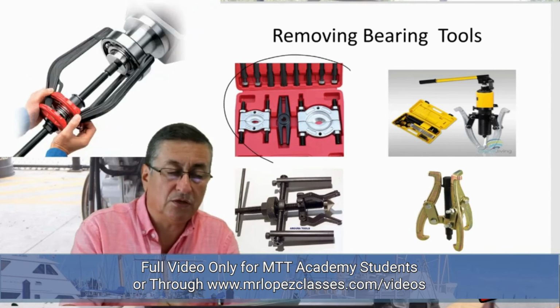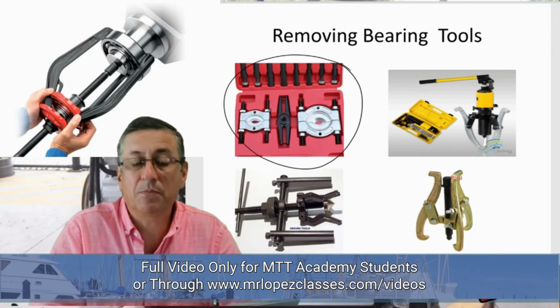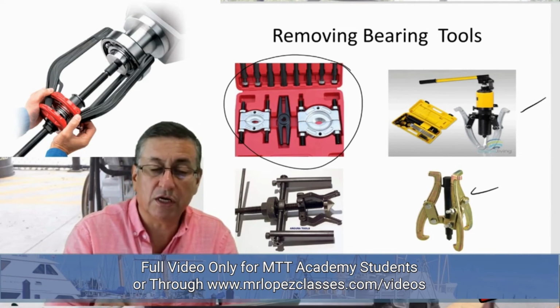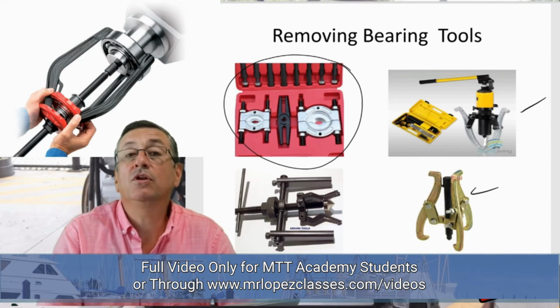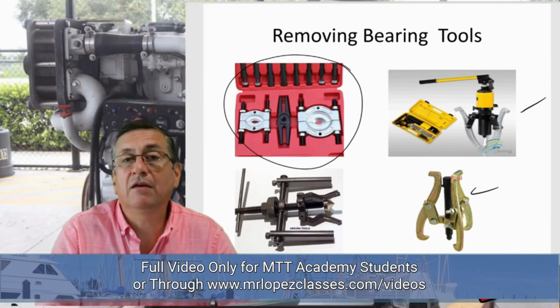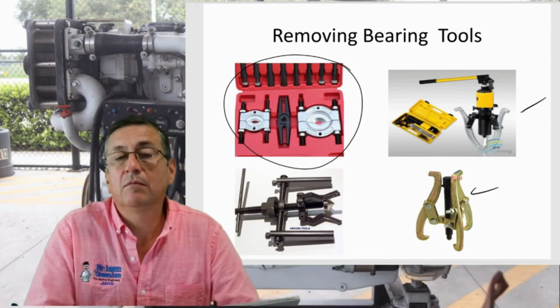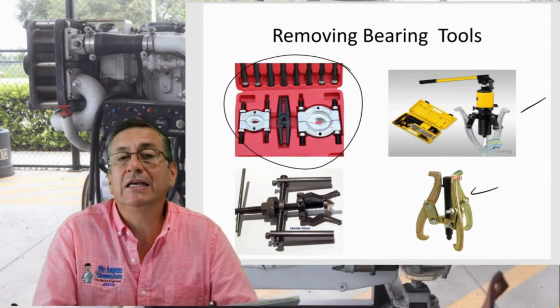These ones are used with the hydraulic press, and these ones are usually used manually in order to remove bearings. You need to be careful when you remove the bearings. Never apply the force on the external ring, because you destroy the bearing. You need to apply the force on the internal ring, because if you apply the force on the external ring, you destroy the bearing.